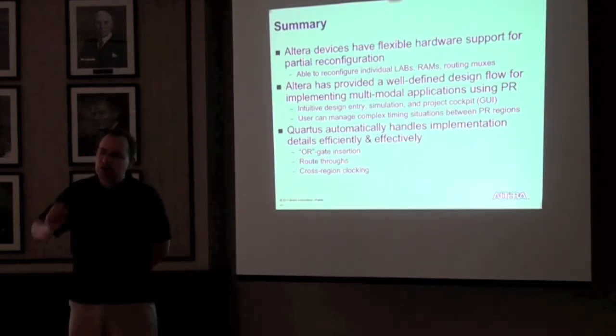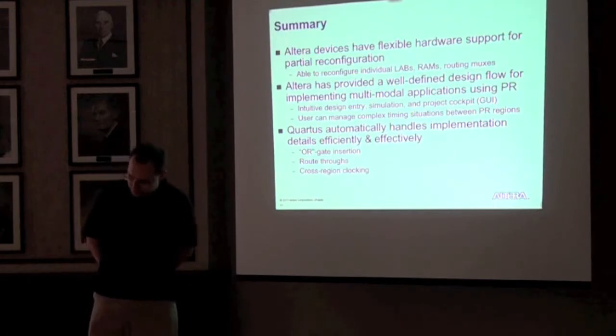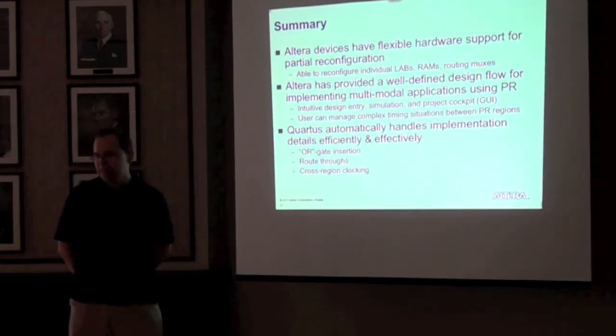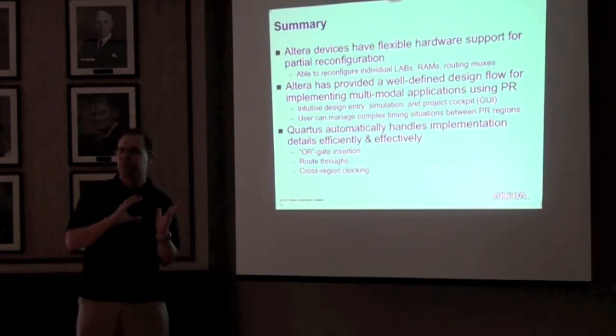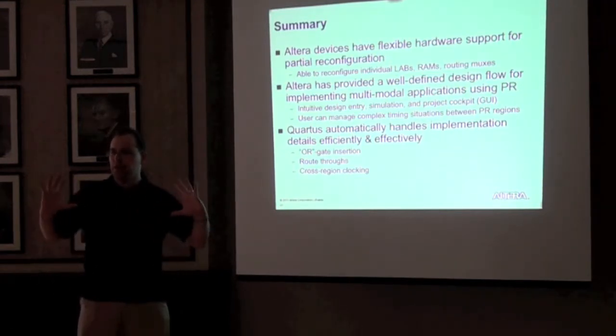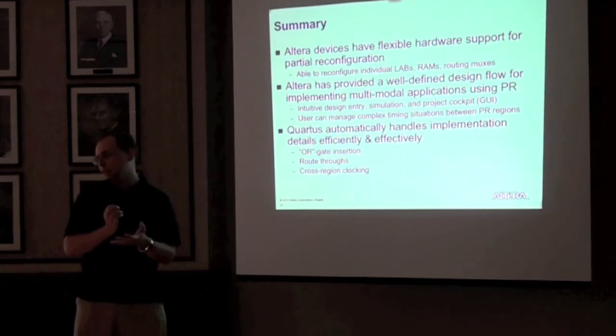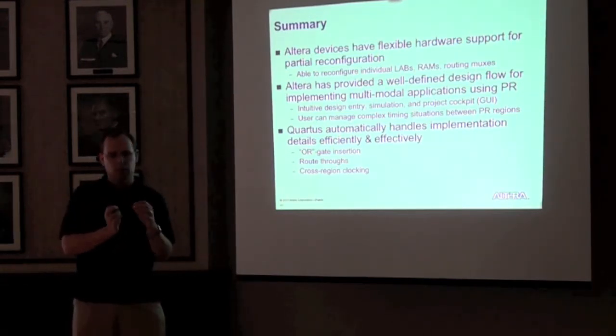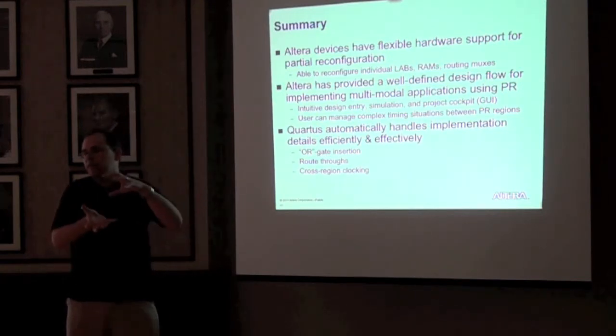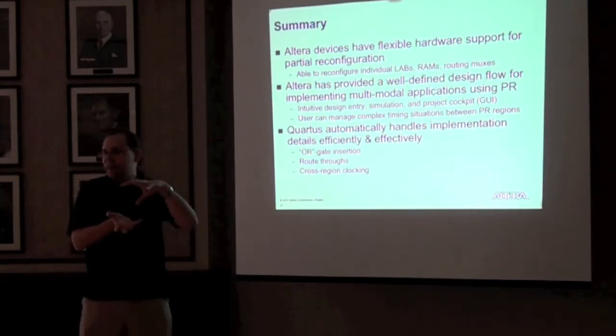So, unfortunately, I don't have the answer to that question. I believe a lot of the state is different than device bring up, where you have different power rails coming up. Here, all the power rails are already up. So, for example, the contents of an embedded RAM will be part of that partial bitstream, so it will be, in fact, well defined.